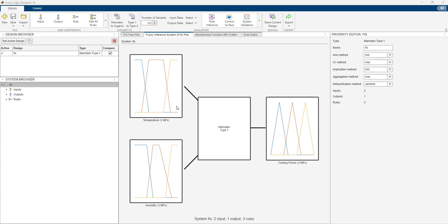The way fuzzy logic works is that you take a physical input, it has a fuzzifier which uses a membership function to create a fuzzy set, and that goes into the inference system, which is also connected to the rule-based system, and with that it creates a fuzzy output. Then that goes into the defuzzifier, which breaks it down into the normal output that can be used. So that's a rundown of how a fuzzy system works.